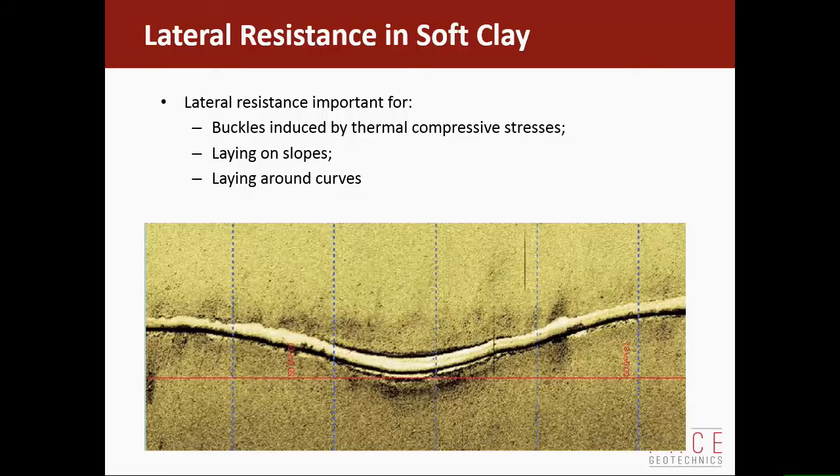One of the things that came up yesterday was the pipelines can actually walk uphill depending on the flow regime and the seabed soils. And that buckle ultimately, because you've got a weaker point there, it tends to feed into the buckle, so you can actually rupture the pipeline ultimately if you're not managing it properly.